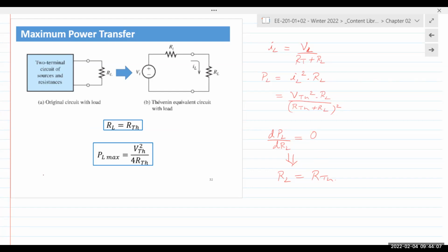So if you have ever purchased a battery, or if you just look up the specs of a vehicle battery, it will tell you there's a spec called cold crank amps. It'll be around 400, 500, 600. It'll say how many amperes of current it can supply at a certain level of cold temperature. Now, modern batteries are very well designed.